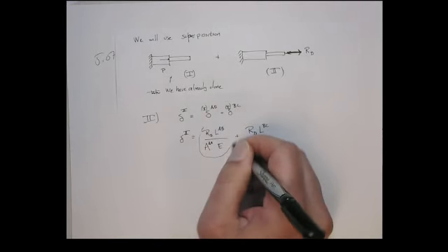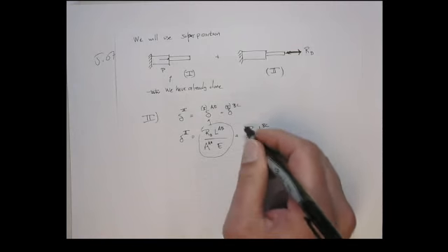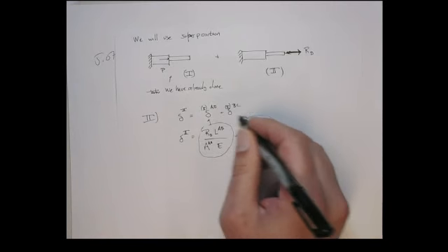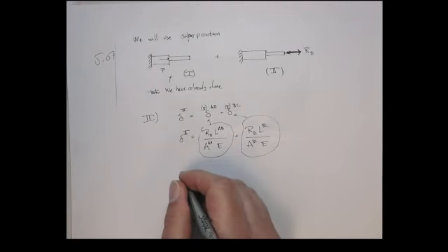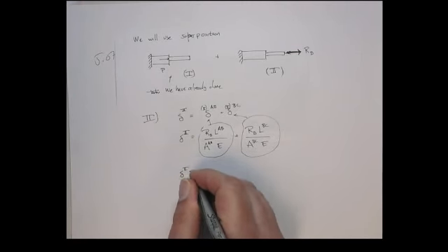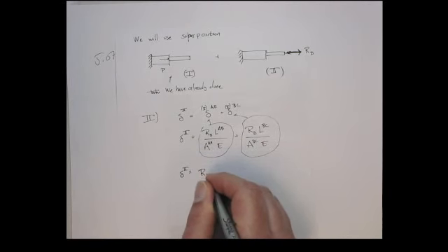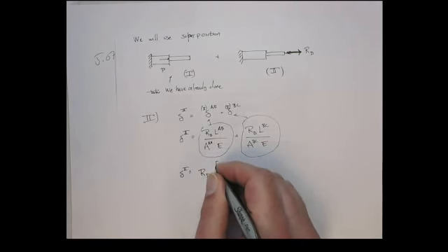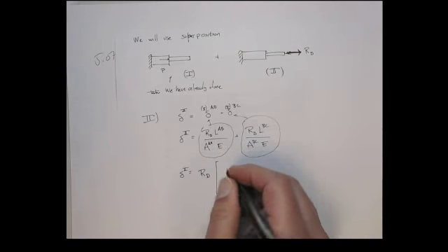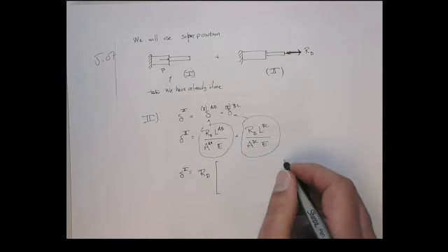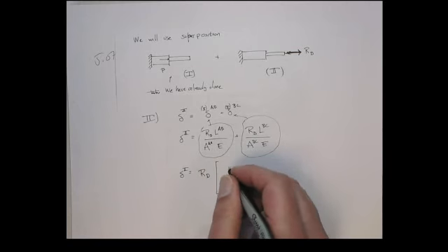So this term here is the elongation in the first section, and this is the elongation in the second section for this loading. All right, so I can take the RD out. Delta 2 becomes RD. Let's put in some numbers here now. So the length of AB, they're both 600, so actually I can take that out as well. Well, let's put it here.